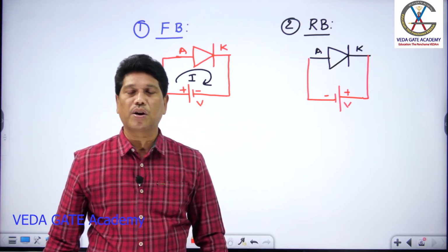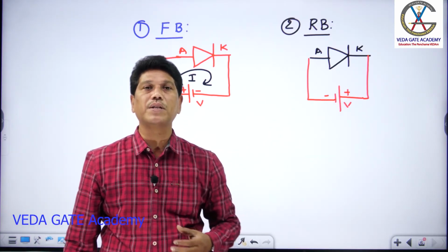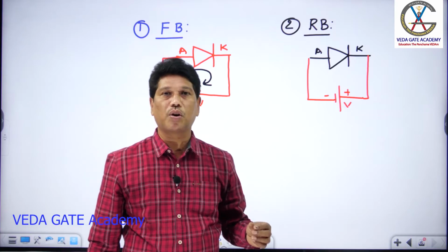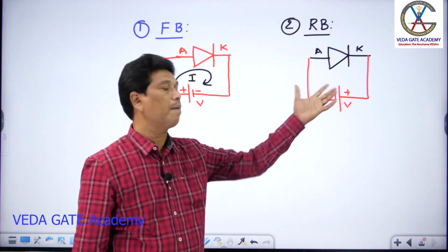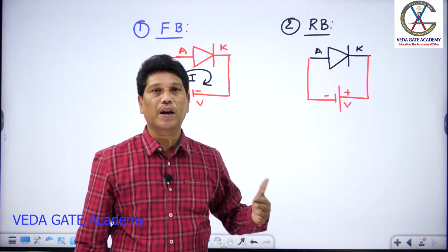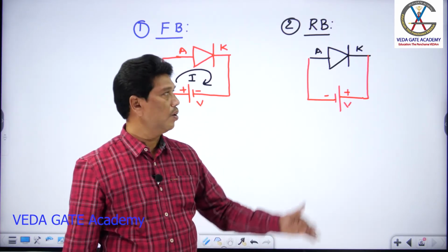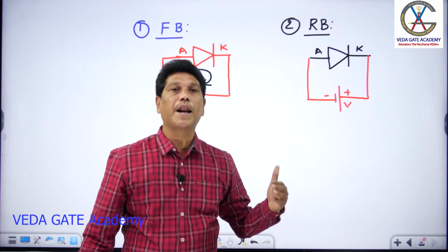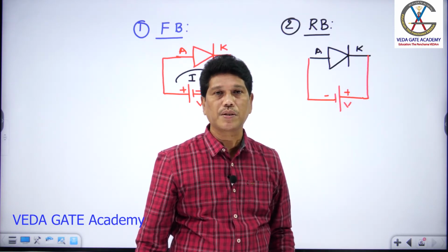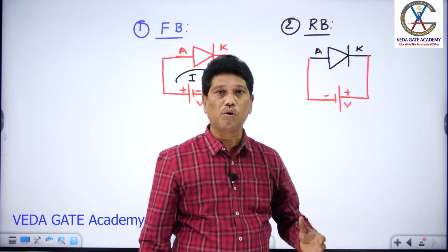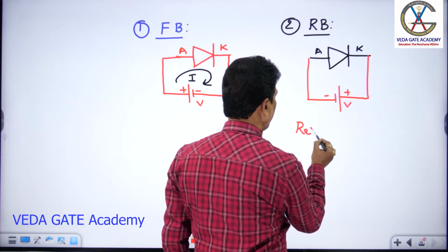That minority current is commonly called the reverse saturation current, I0 or IS, and it is strongly dependent on temperature. It is about microampere for germanium and nanoampere for silicon. Ideally no current flows; practically only minority current flows, which is negligible. So in reverse bias, the current is mainly due to minority carriers, which depends strongly on temperature, not on voltage. By that, the current in reverse bias is called the reverse saturation current.